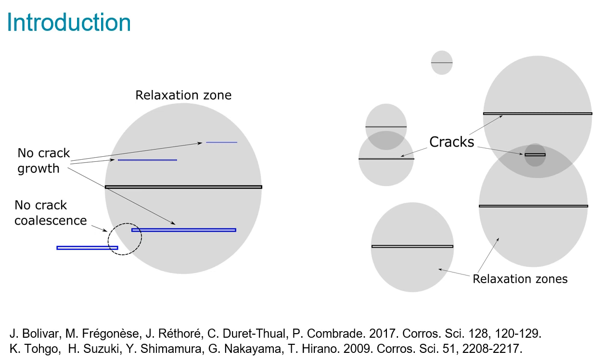A shielding effect is due to the relaxation zone around the pre-existing crack flanks. This zone, which is also called inactive, is usually presented as a circle with the pre-existing crack as a diameter. To reduce the amount of computation, some authors assumed that in such regions, crack may not be able to propagate and coalesce with others.